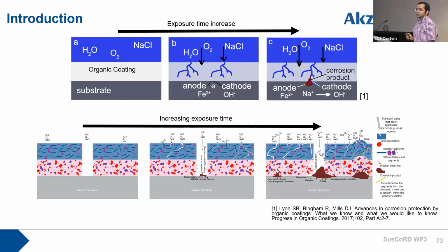But organic coatings are not only made of polymeric binder and curing agents nowadays. There are several different inorganic and organic fillers and different additives added, but also we can have different layers of organic coatings on top of each other. So it is important to understand how all these different ingredients, pigments, fillers, and additives will affect this percolating network formation and how they will affect the performance of the coating.